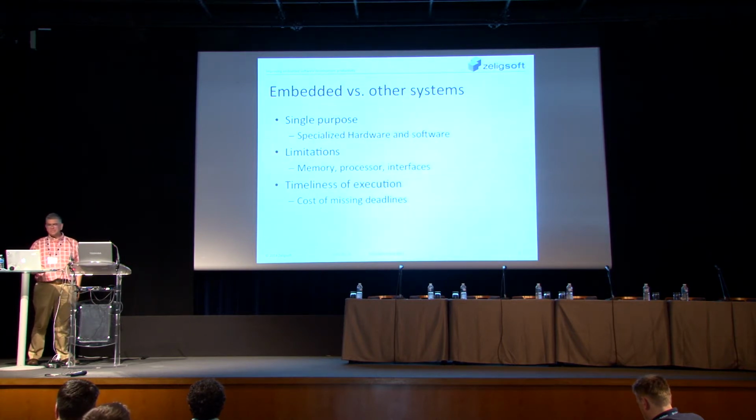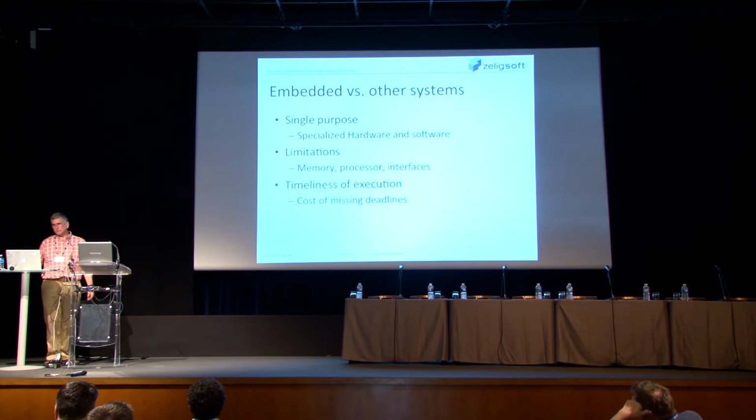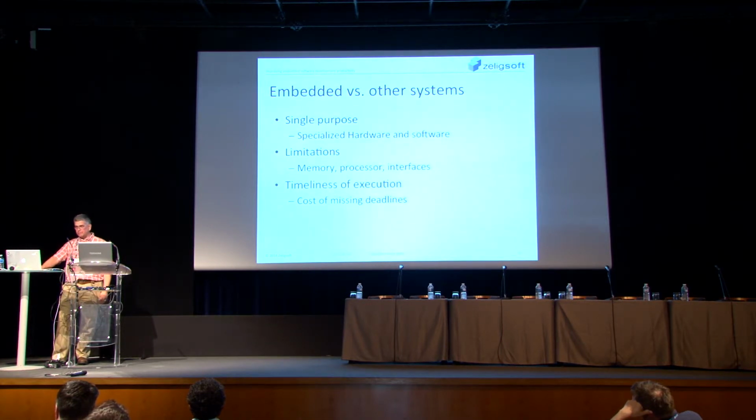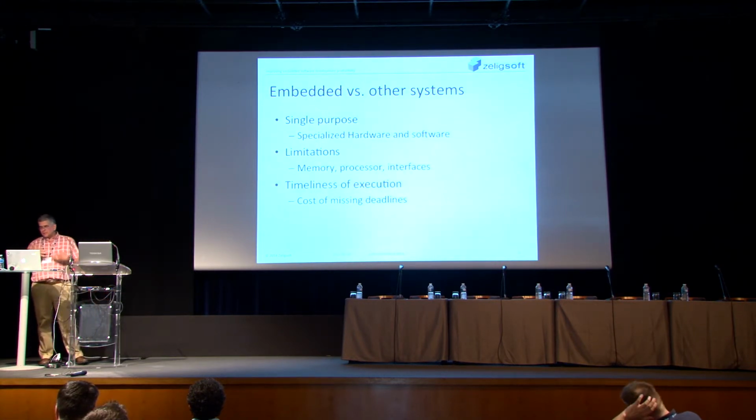Another very important point is timeliness of execution. In real-time systems, which a lot of embedded systems are, there is always a cost for missing deadlines. There can be soft real-time where the cost for missing a deadline is, well, not that bad. So it takes 3 seconds for you to pick up a call, for the call to connect, as opposed to 1. Well, you're not going to die about that. If it takes 5 minutes and it's an emergency call, then yes, but so there's different costs.